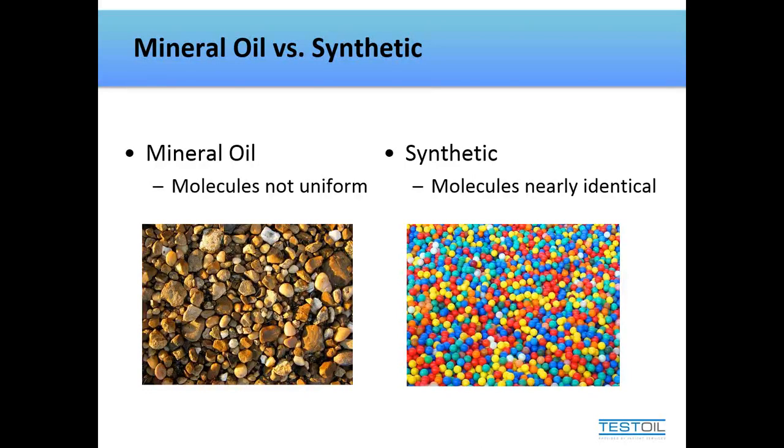Now, with synthetic oils, this will be equal to filling that room up with everything the same size, all tennis balls or all beach balls or all basketballs. The door will fit nice and flush on these balls. It will run nice and smooth. Every surface is equally loaded. That's pretty much how your synthetic works in your machines. And when these synthetics are engineered, the molecules are engineered just for that reason, to have everything uniform and identical.